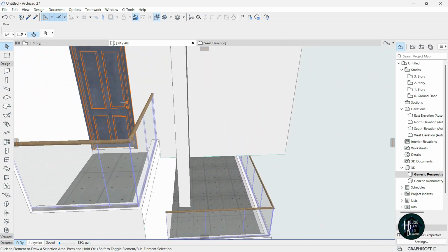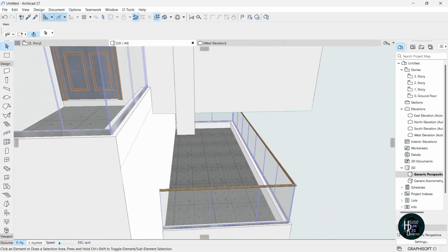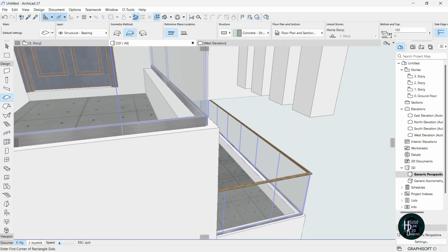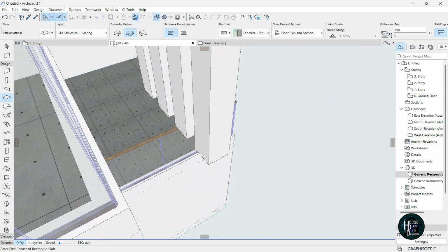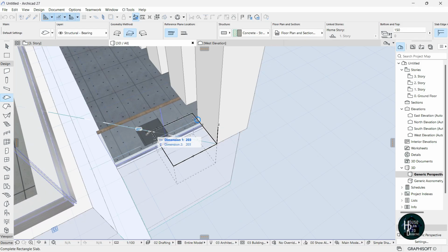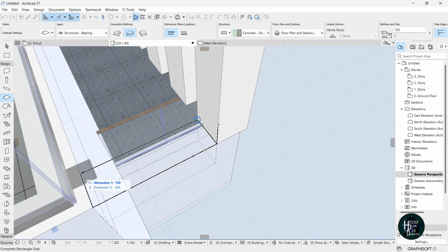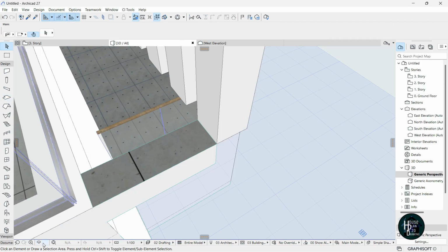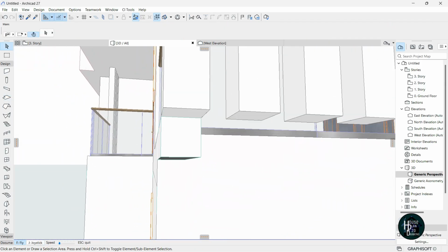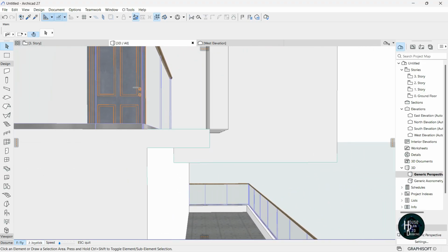So the next thing I wanted to do is to come and perfect the design for this side here. So what you want to do for this side now is you want to hold down Alt, select on this slab you are seeing here, click on the slab. Now just click this edge here. All right, put the cursor here, allow it to load up, and just stretch it to this side, then click. Okay, once you do that, try and just make sure it's showing how it's supposed to be and it's not looking weird.